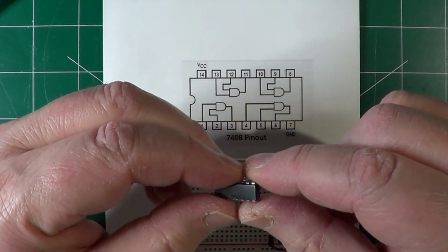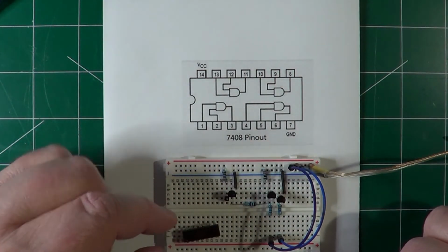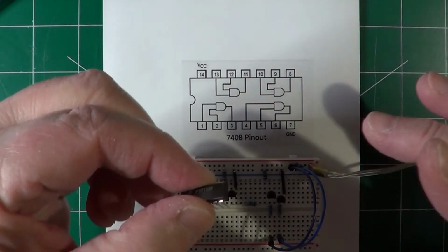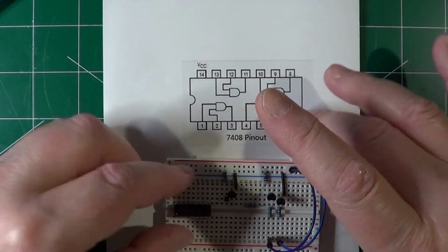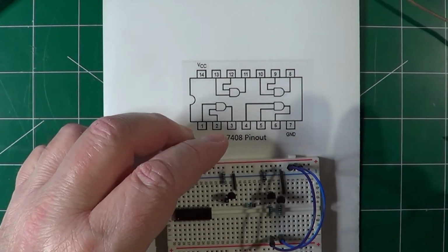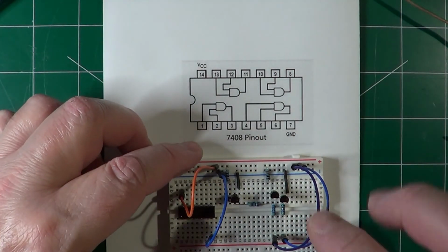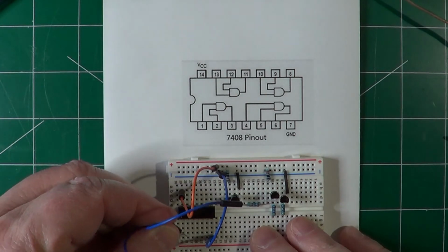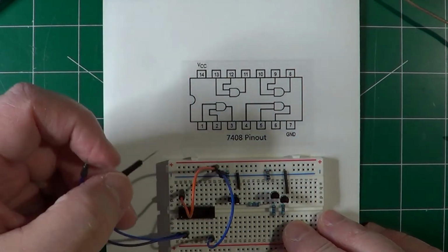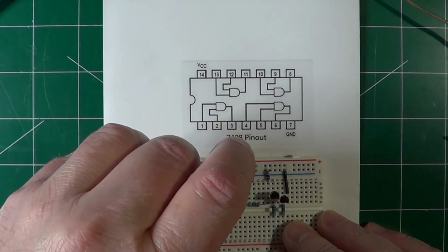This little IC covers 4 circuits identical to the one currently assembled on the breadboard. Let's now put the IC on the breadboard and connect the power to pins 7 and 14. Pins 1 and 2 are used for the inputs of the first gate in the IC, which for now we connect to ground, which is the logic 0.